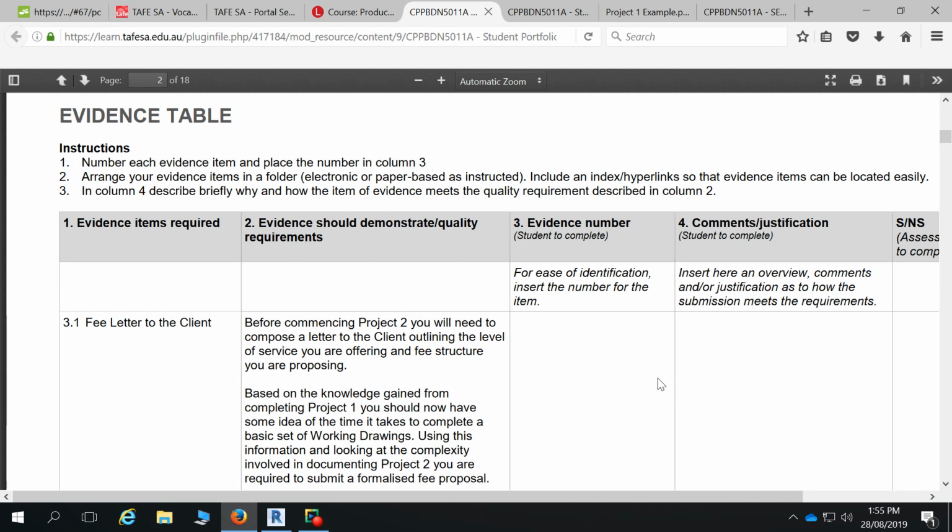So it's possible. It's just that one of the big benefits of using Hebel is it's very good acoustics, and it's quite good as an insulator as well. So it adds to your R value to the wall considerably. So if you start putting blue board, those sorts of sheetings throughout everywhere, you've really sort of defeated the purpose of using that product. So you've got to try to really minimise that. So sometimes with a job like this, it can take almost a day. Not that I'm going to expect you to take that long, because it's been worked out, but to actually figure out how that panel is going to work and try to reduce the shortcuts.